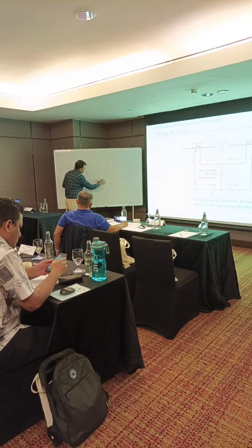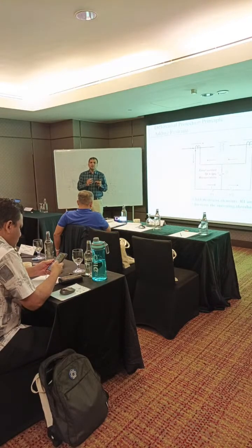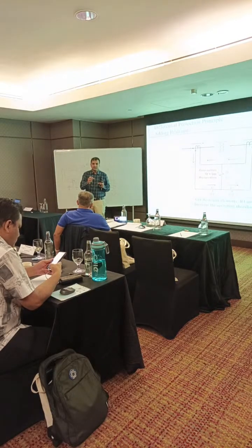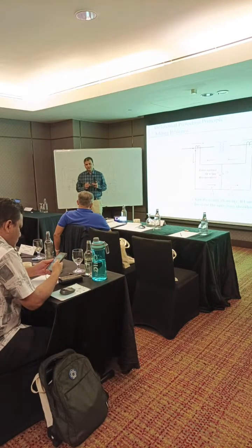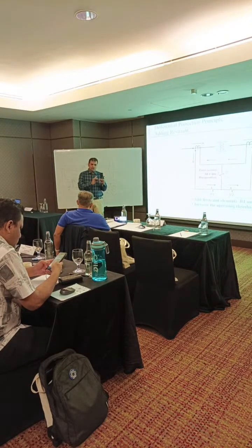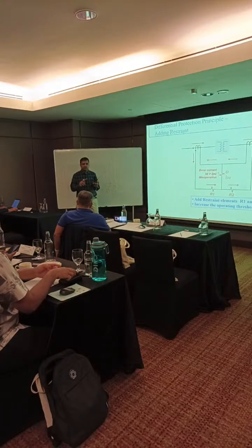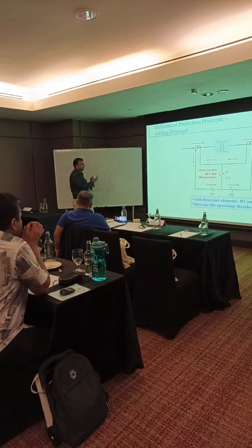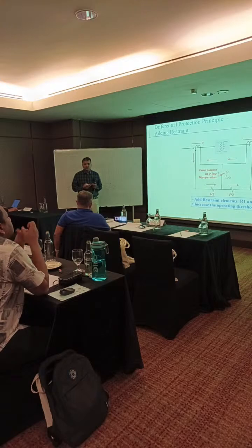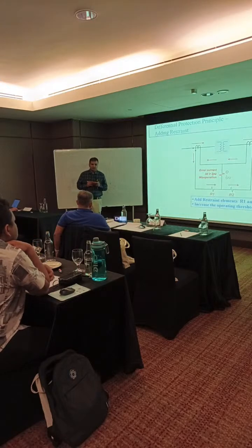Suppose this margin is very small, like yesterday's setting. In that case, you cannot find two points, so you can follow this method, so that the I bias will be constant and differential current may be increased. Our aim is to find the point when the relay trips. At that point, we note what is I bias and what is I differential. Once we get two points, we can calculate the slope. In this way, you do not require any template.